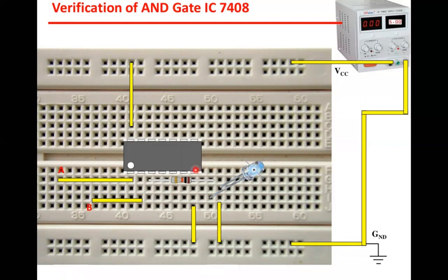And because this is pin number 7, these are all interconnected to each other. So from here we have connected to the ground, and all this horizontal will be interconnected to each other. In the breadboard, these are vertically interconnected to each other, and this horizontal will be interconnected to each other. So 7 is connected to ground. Here you can see it, and the other terminal is connected to the ground.